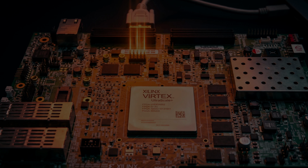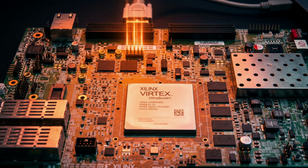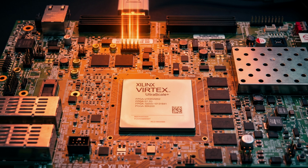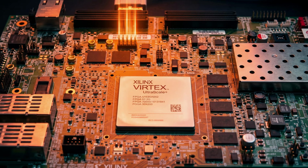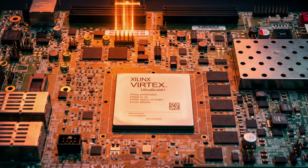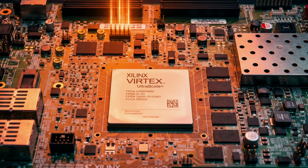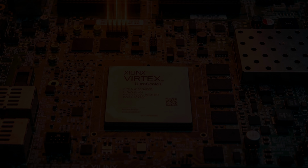The Bitstream file and the FPGA board are ready. Now a bridge is needed between them to load the Bitstream file onto the FPGA board. That bridge is JTAG, Joint Test Action Group, a 4-wire serial interface, the standard method for hardware programming and debugging since the 1990s. TDI, data input. TDO, data output. TCK, clock. TMS, state machine control. These 4 wires will carry the Bitstream from the computer to the FPGA.